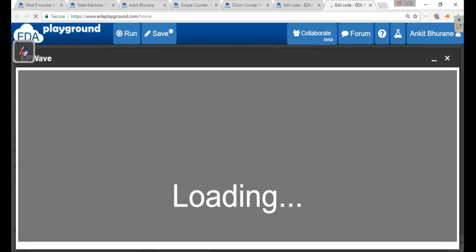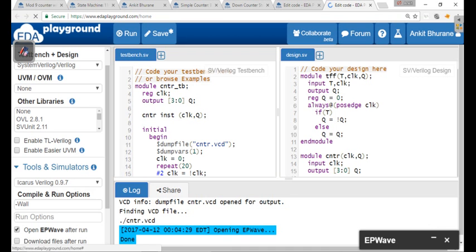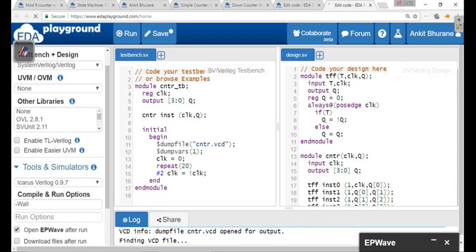And you should be intelligent enough to capture where to give that 0. You can't initialize that q equal to 0 here, just because this is an instance. An instance can't have this output as regs. They must be wires. But then how do we specify the initial value? We are specifying that as 0 in the flip-flop definition itself. So that is how the trick works.